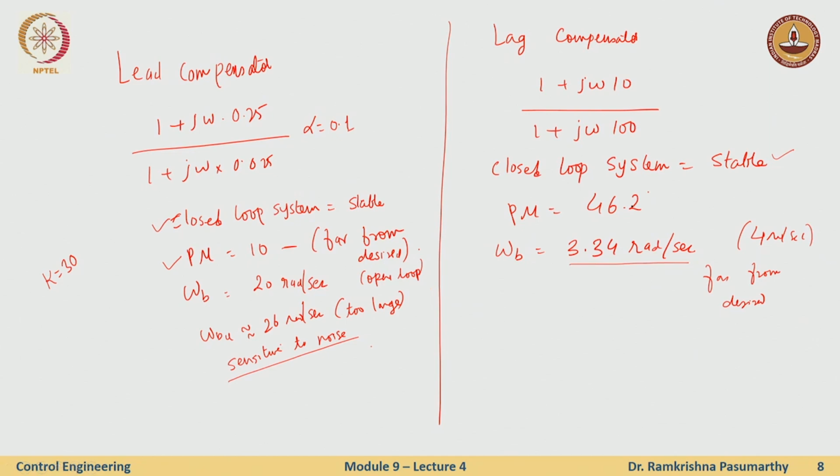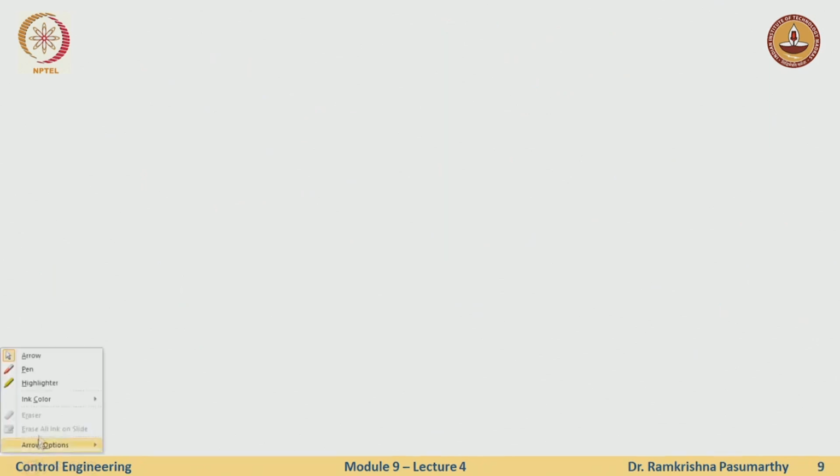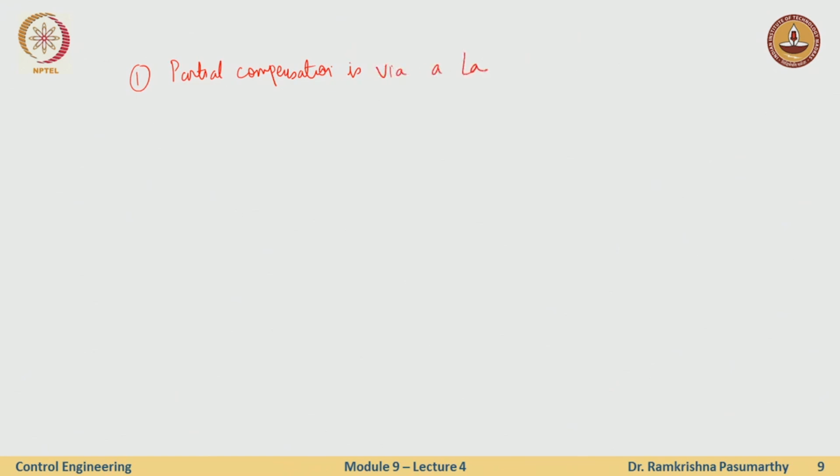As a rule of thumb, which may not have very proper justification, we first design the lag compensator, so partial compensation via a lag compensator.